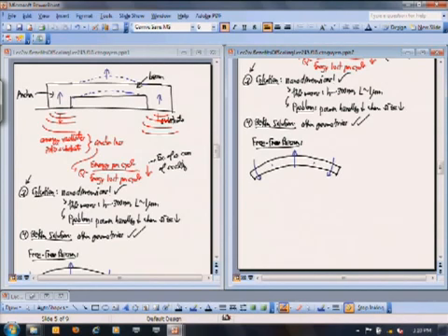Where the transverse motion, which means motion in the up and down direction for this, equals 0. Okay? And so basically put your anchors here. And you lose very little energy. Putting your anchors there makes your energy losses go away.